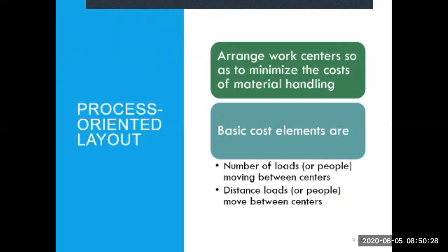When you arrange the work centers to minimize material handling cost, there are two elements you have to take into consideration: the number of loads, either of people or materials, moving between the centers, and also the distance the loads or people move between the centers.